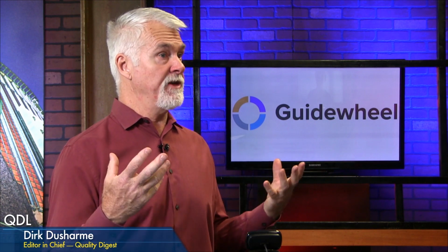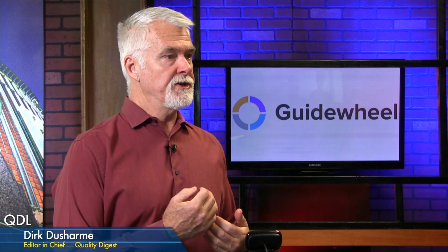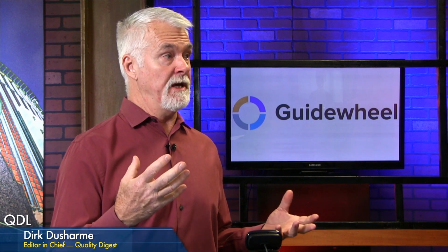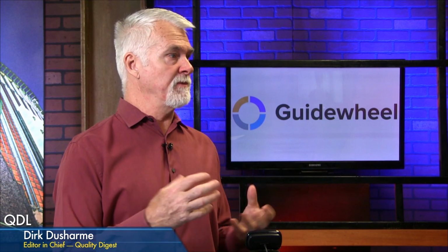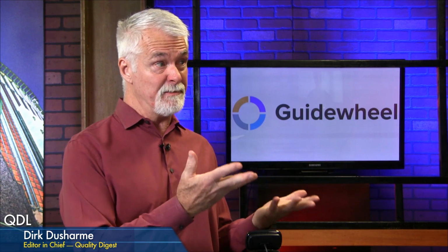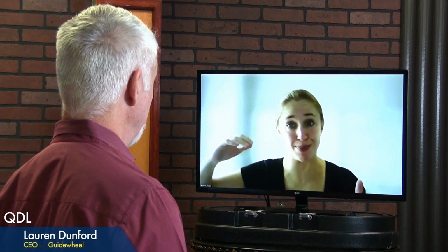Okay, so what else does it tell you besides just the machine is running or not? I guess one thing that comes to my mind is if you start seeing the current increase, that might be an indication that maybe you have a motor going out or bearing problems, something that maintenance needs to look at. Is that part of it? Absolutely. There's so much you can know about machine health from that second by second pattern.